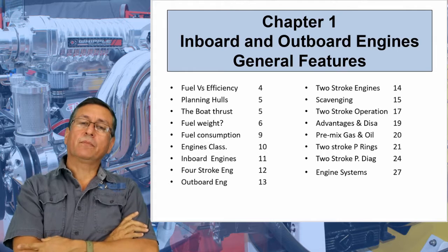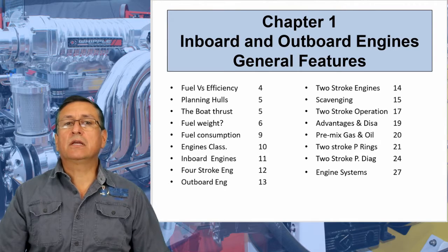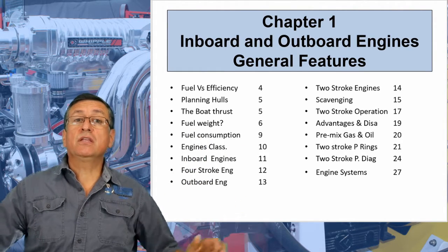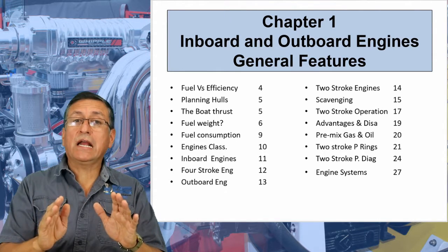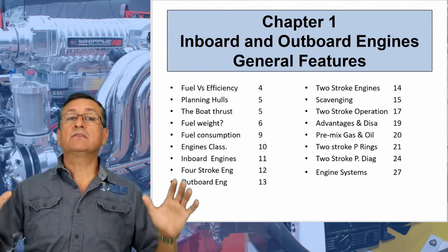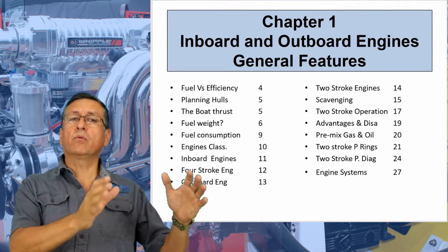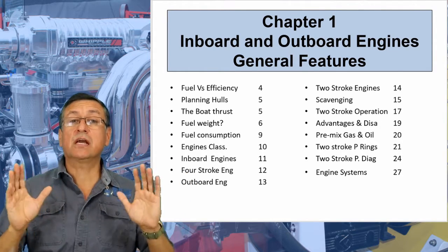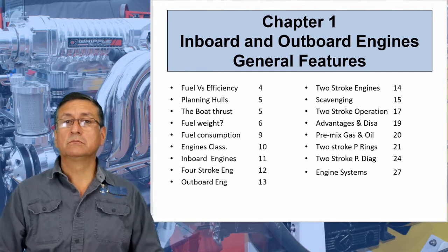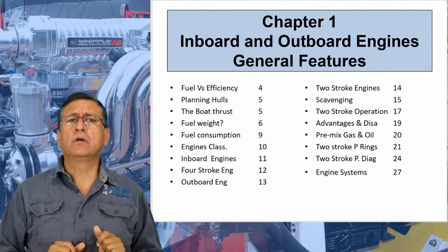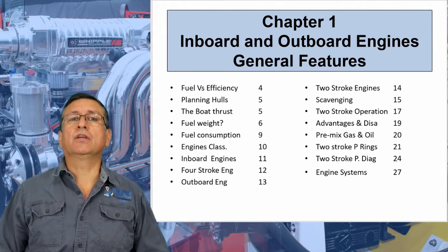You remember that I explained in the previous class on diesel that the inboard diesel engine is basically an automotive engine adapted for marine applications. The inboard gasoline engine is exactly the same. It is an automotive engine adapted for marine applications. The adaptation is exactly the same. We are going to replace the radiator with a heat exchanger, and we are going to improve the exhaust manifold in order to avoid high temperature inside the engine room.